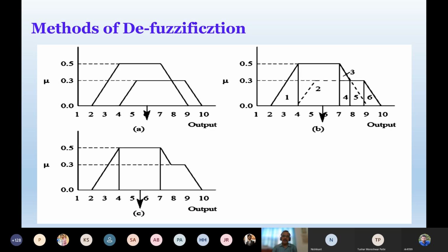And you know how to find out the center of area. That is nothing but 2/3, 1/3. For this type of triangle, the center of area will be at 2/3, 1/3 division on the base. So you'll be getting the center of area. For this rectangle, you know how to find out the area and center of area.